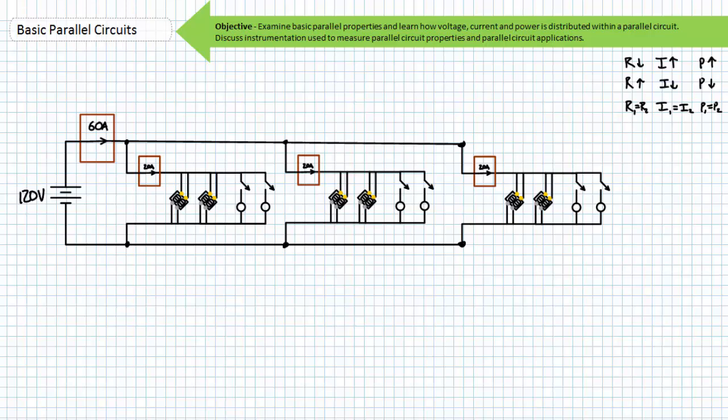Water heaters, typically 240 volt AC loads, are normally wired independently from the 120 volt AC bathroom outlets and light circuits. The point is, assume nothing, trust no one, always test and verify. You must properly lock out, tag out, and test and verify that all sources of hazardous energy are not present, nor can any build up during the course of your maintenance procedures.